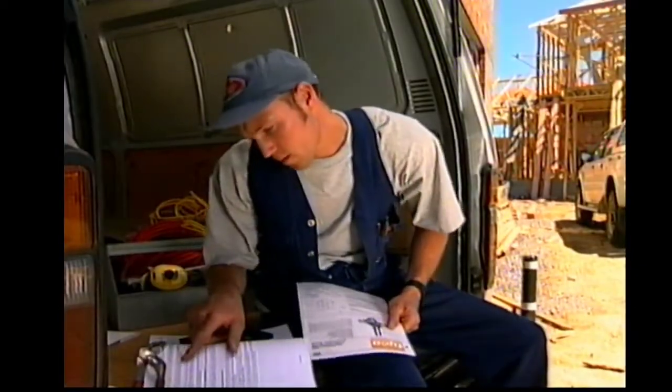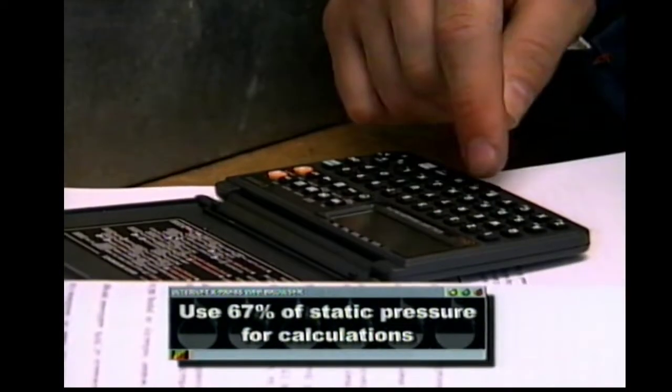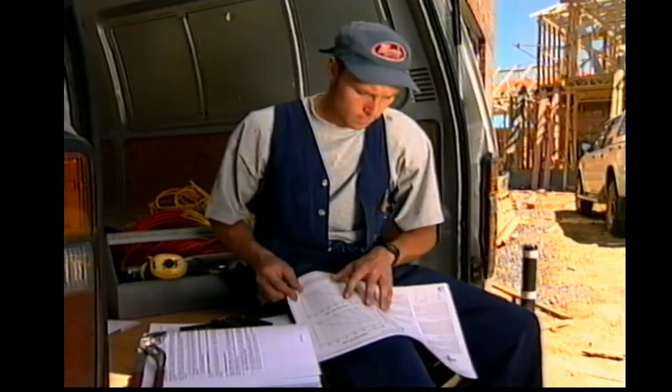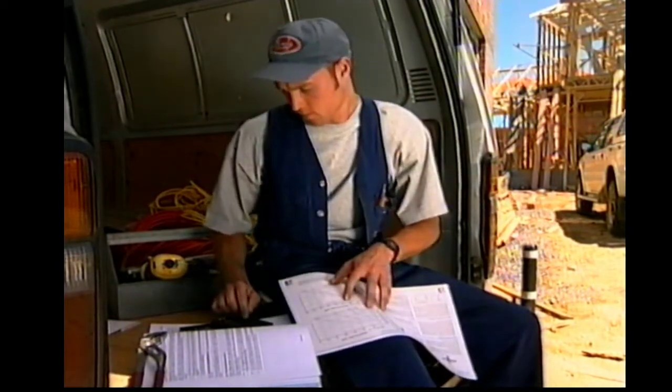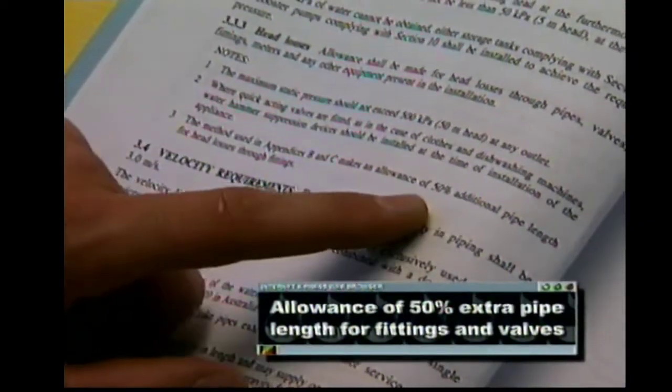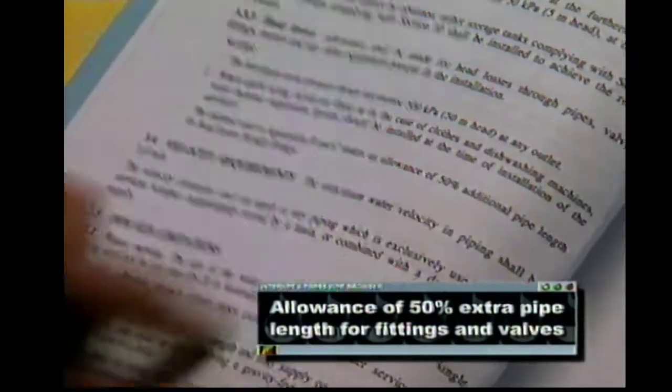Now, when designing, these days it's acceptable to use a design pressure of 67% of the static pressure in your calculations. This simulates a minimum pressure. When calculating for pressure or head losses, your standard sizing tables include 50% extra pipe length for fittings and valves.